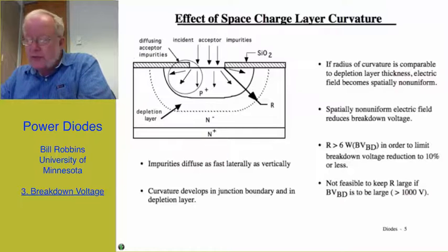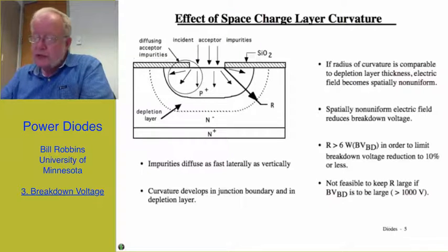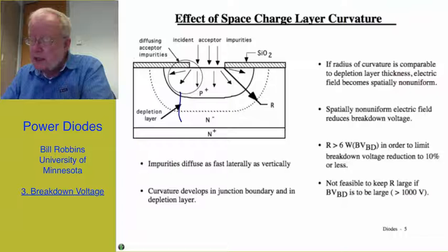The p-n junctions that we formed are normally formed by diffusion, and the result of the diffusion process, which I've highlighted here, is the metallurgical boundary having a radius of curvature, particularly outside of the area where the window was opened in the masking of the diffusions in the process of fabricating the p-n junction. As a result, when we reverse bias this p-n junction, we have the same type of curvature in the depletion region. Here in the plane parallel section that I've outlined here,